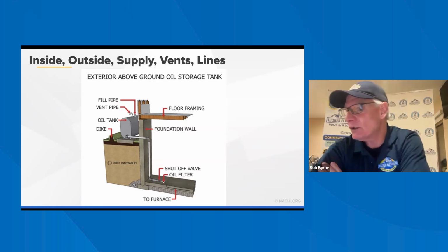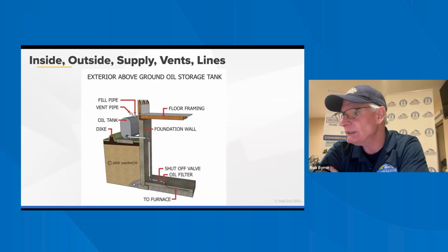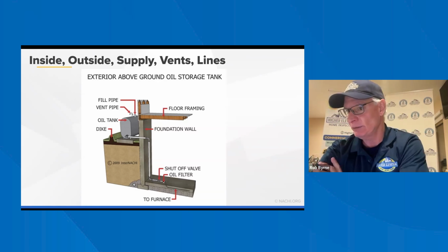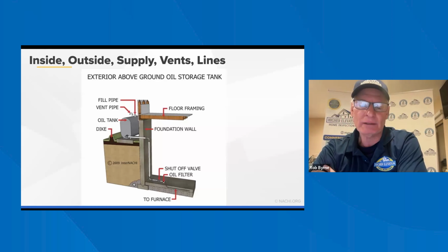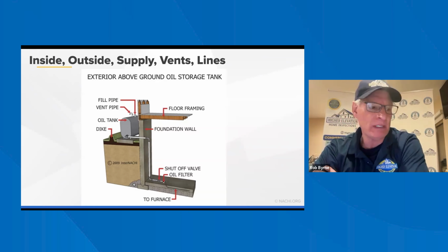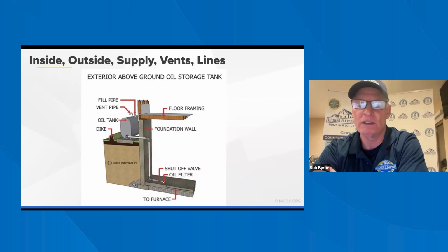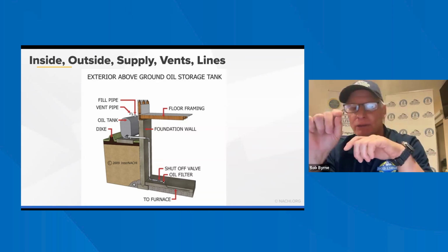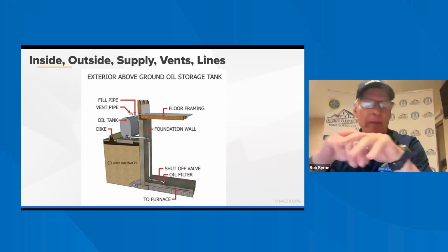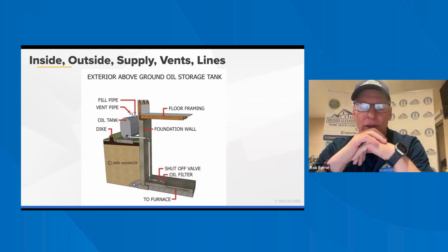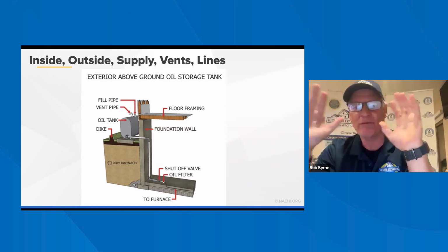Inside and outside oil tanks for inside dwellings should be of such size to permit installation and removal from the dwelling. A lot of times you go on house inspections and these oil tanks are in the basement, but they're behind finished walls. We literally can't even look underneath it or inspect it. If you can't do that, you have to put it in as a limitation. Sometimes they just have this little cutout so you can read the gauge to see how much oil you have in it, but you can't tell anything about the oil tank around, the underneath or the sides because it's finished.